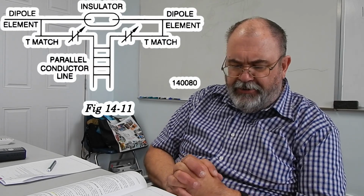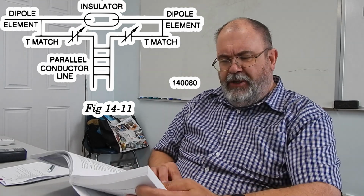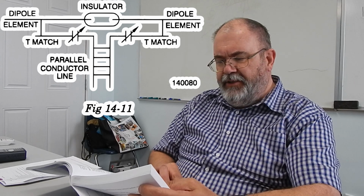Here we're using 50 ohm transmission lines. So right there, we have a 1.25 to 1 SWR, or worse, just because of that. So we need some way to match these impedances, because when they match, everything's happy. The T match is meant for ladder line or parallel conductor line. And there's a nice little picture of it on the very top of page 14-18, figure 14-11.